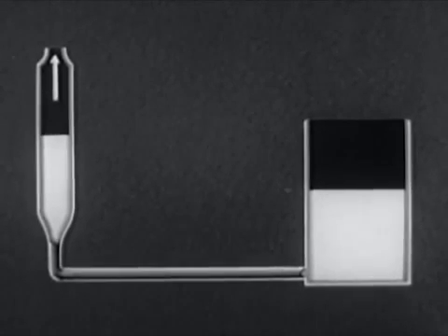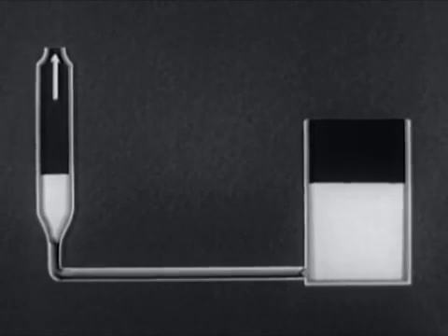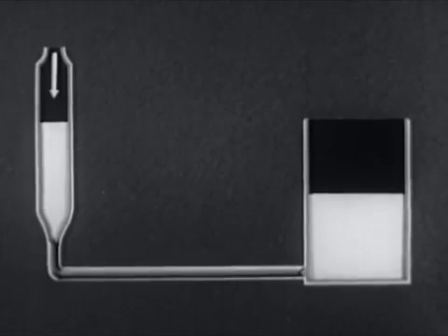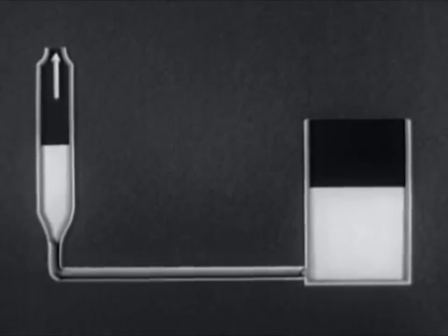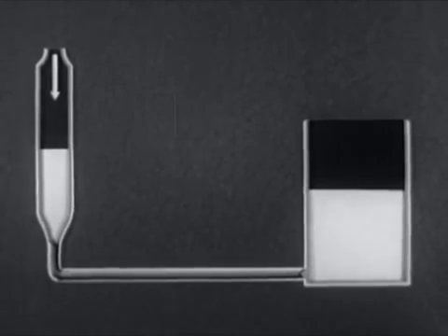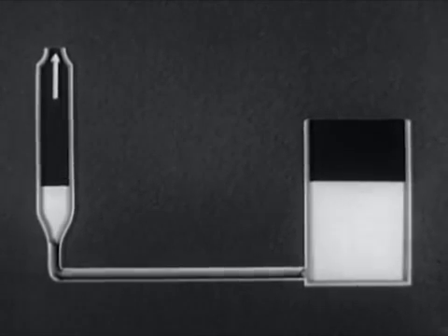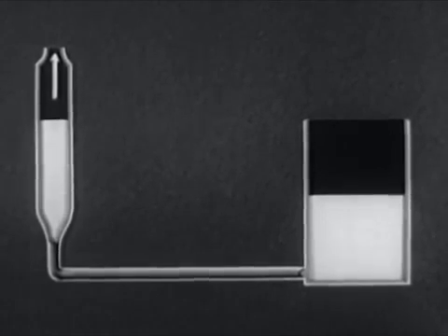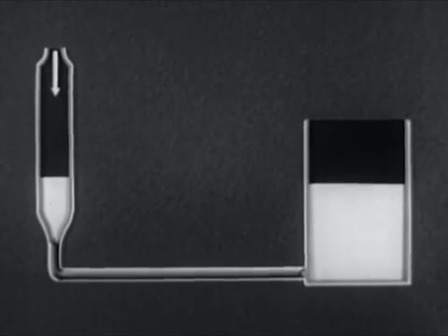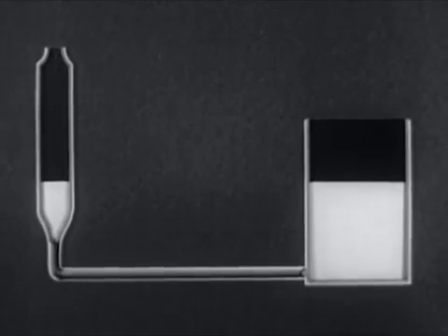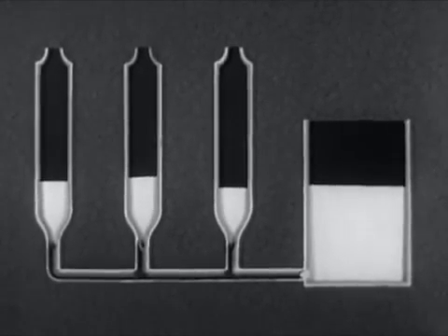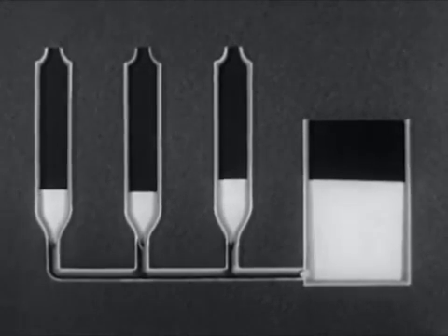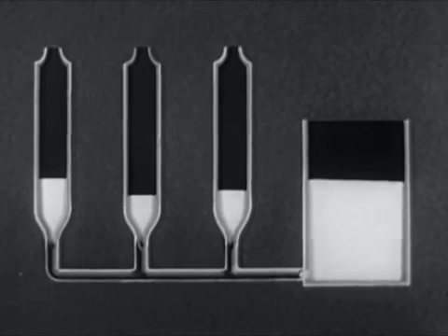In a device such as this, if the liquid in the tube is subjected to varying pressures, the level will rise above or fall below the level of the liquid in the reservoir as the pressure is decreased or increased. Reading of liquid levels provides an accurate means of determining pressure difference. Additional tubes may be added, each connected to a different value of pressure, and each will indicate that pressure accurately, regardless of pressures in the other tube.